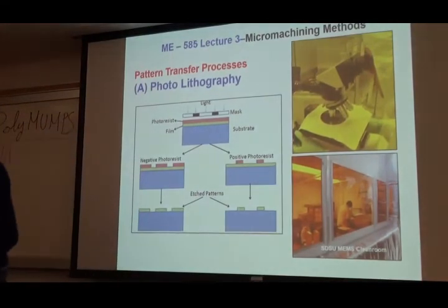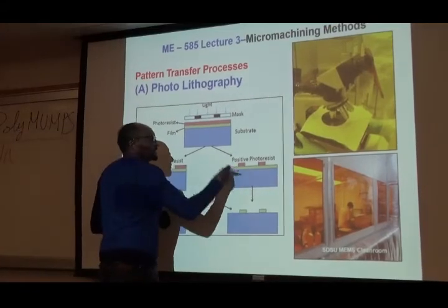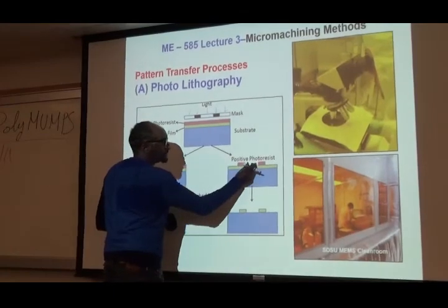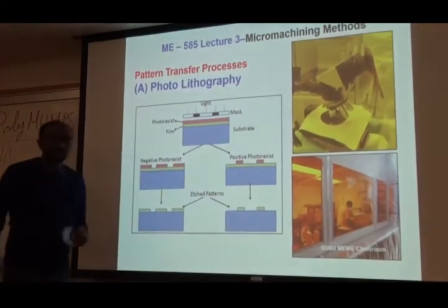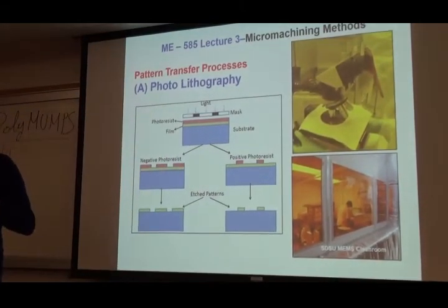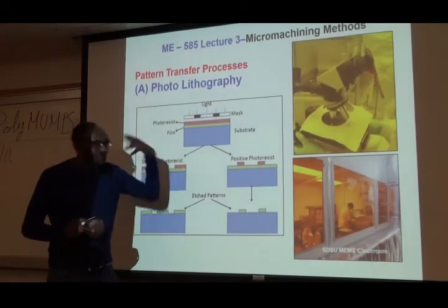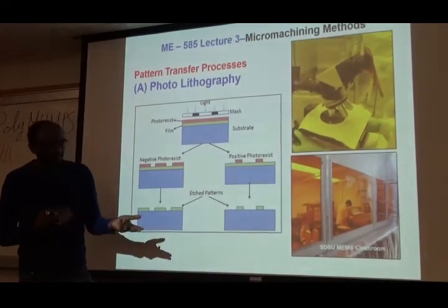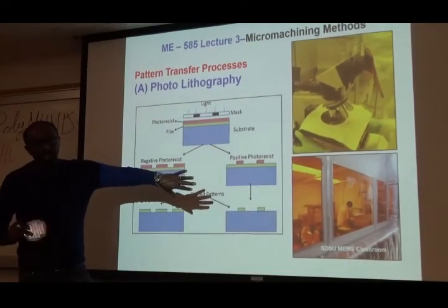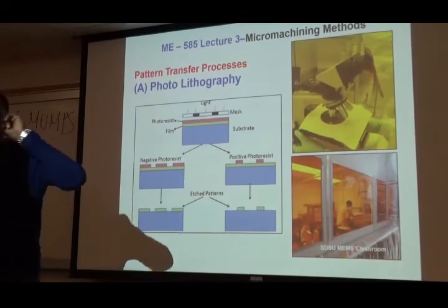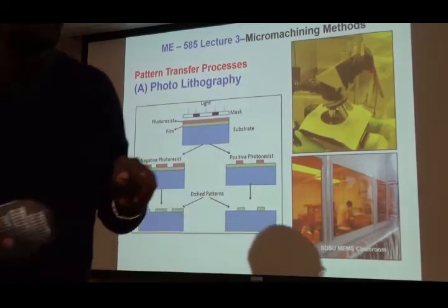It's going to wash it away, because it's a sacrificial material. Its mission is over. It's gone. Then at that point, whatever material that you want is going to be here, here, and there. So the whole process of putting a photoresist and then exposing it to a UV light and developing it and then eventually stripping it away is called one litho process.